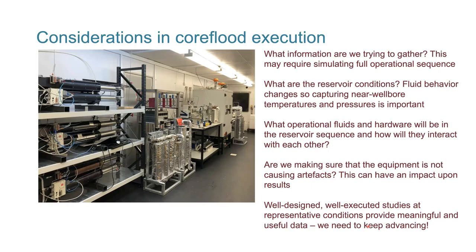So, doing a test at room conditions versus reservoir conditions, using the technology available to get closer to reservoir conditions is going to give us better data, more meaningful data to make better drilling decisions. Because fluid behavior will change, viscosity will change, near-wellbore temperatures and pressures, very important. Capturing everything as close as possible. If we're looking at an acid, for example, typical acids could, every 10 degrees centigrade increase in temperature could double the effect that they have on the reservoir, double in the strength of the acid, essentially. So making sure we're as close as possible to reservoir conditions is vital, and using the technology.